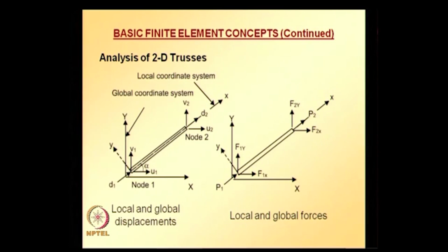The equations for these elements are well known in the structural engineering field and usually are covered in traditional courses on matrix structural analysis. Element equations can be derived from the axial deformation element using simple coordinate transformation.